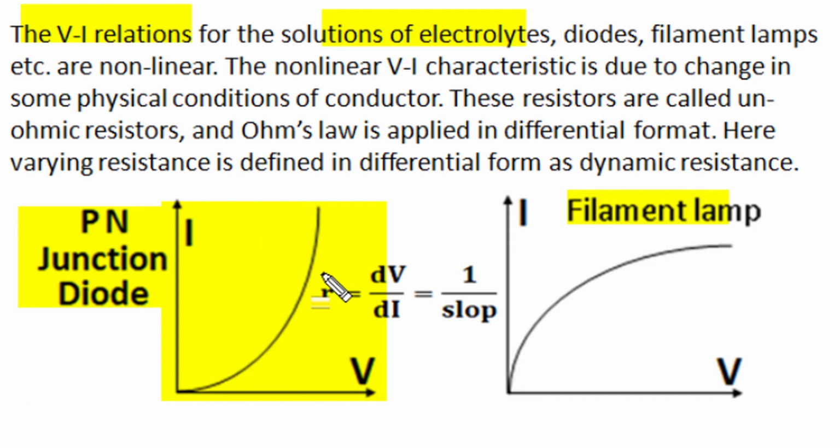They are curved relationships between current and voltage, and such curved relationship represents some variation in physical condition of conduction, as in PN junction diode the depletion zone formed between P side and N doped side at PN junction reduces its width as we increase applied voltage, and due to that the slope of IV characteristic, which is inverse of resistance, changes its magnitude, and such varying resistance is called a dynamic resistance. And as slope of IV characteristic is increasing, the dynamic resistance of PN junction diode decreases as we increase applied forward bias voltage.